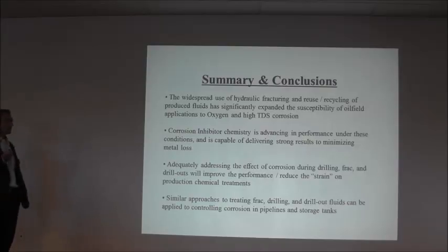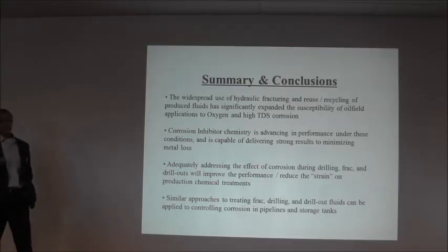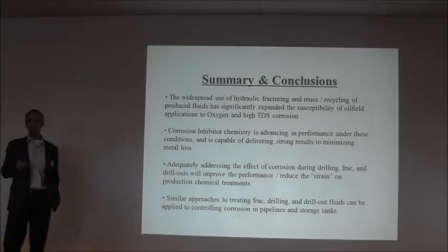And I'll touch on one last thing, and I'm sure any of you who have worked on the friction reduction side of fracking are very well aware. It's probably hard to find a single ionic species in brine that kills an FR more than dissolved iron.